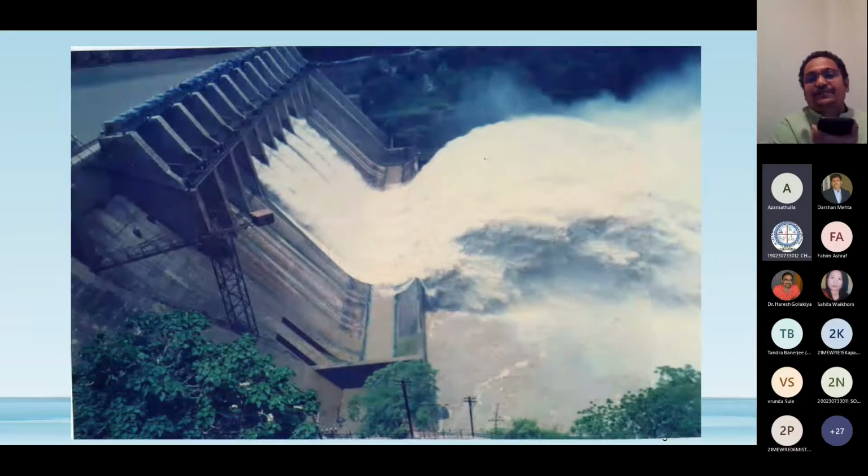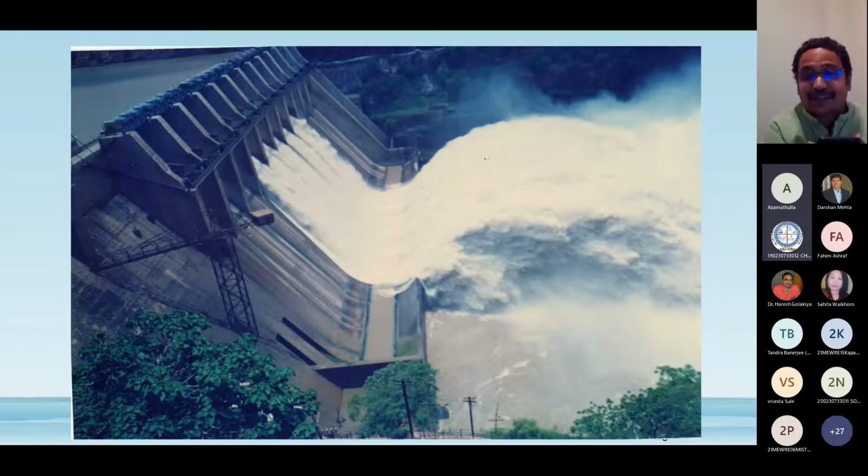Okay, this is one of the dams from South India, from my state, Srisailam Dam. Here, some lip angle problem happened. You can see the theoretical jet. We think it goes very far theoretically, but in reality, model and prototype conformity takes place. Due to air resistance, you can clearly observe the jet. The lip angle, I believe, they considered 30 degrees, so the jet is falling immediately downstream of the bucket. So they have a problem whenever it is the rainy season.